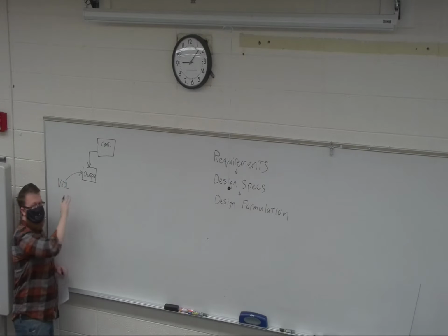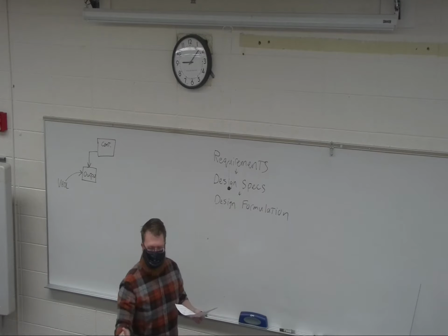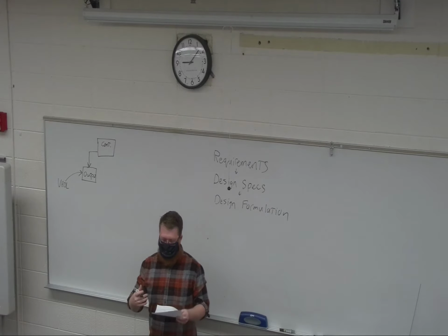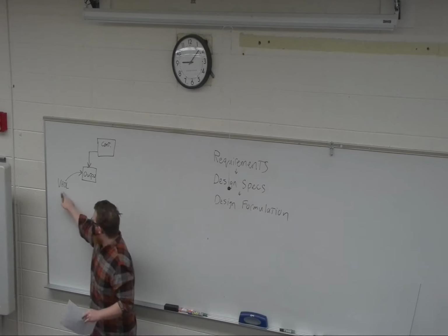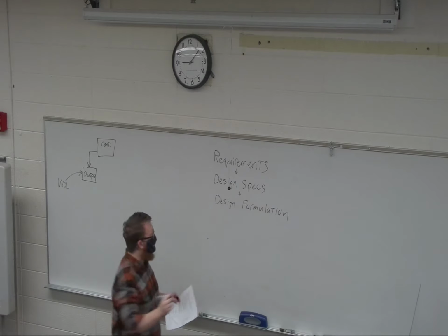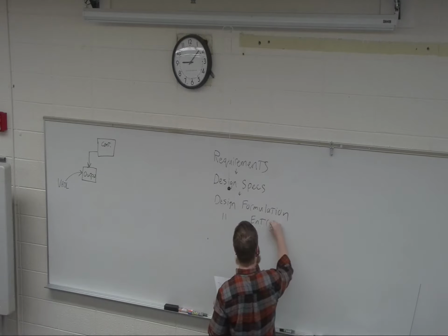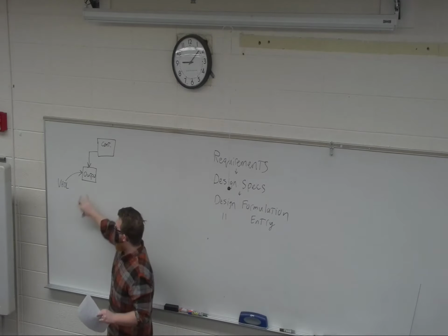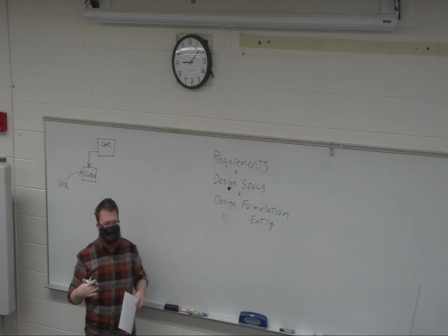So your block diagram is this conceptual level, how are we going to put this thing together, and then the VHDL comes later when you actually just implement it. What we call this, the VHDL that you're plugging into it, is the design entry. Right, so top level, throw some VHDL in, we call that design entry.